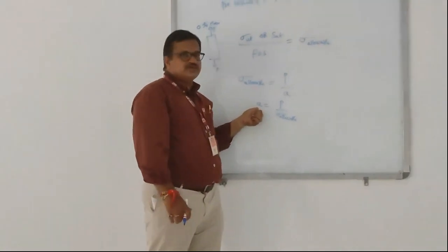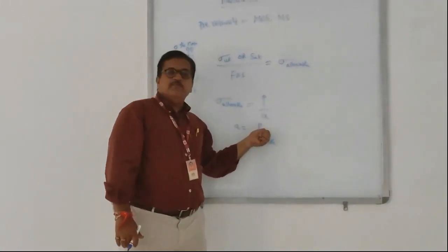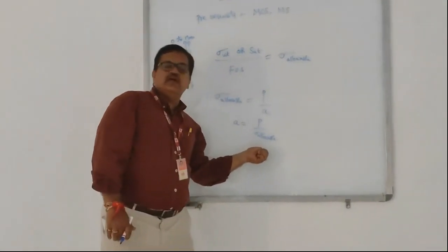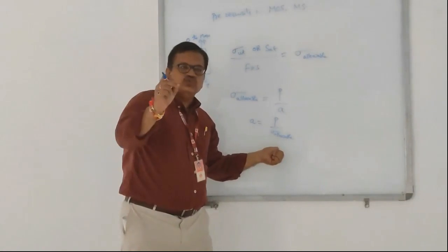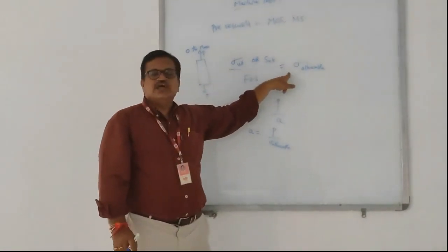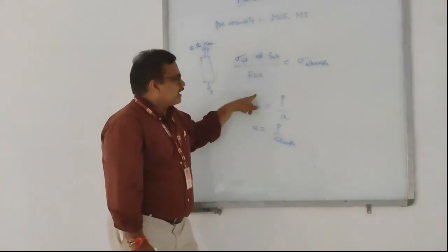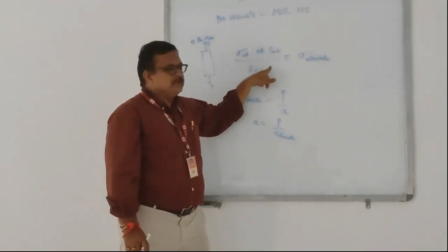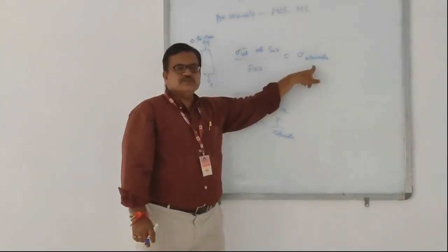You can change the cross-sectional area so that the member is going to withstand 2 tons of load, and it is made of a certain material. Let us say it should be made of mild steel. Mild steel has a certain ultimate stress. For the bar, you are applying a factor of safety of 2. Then SUT by factor of safety will give us allowable stress.